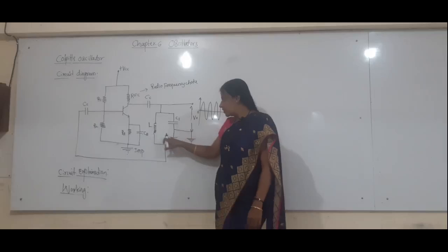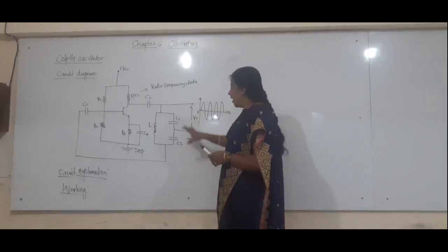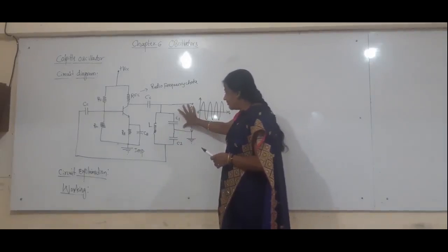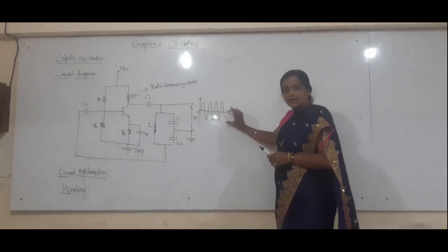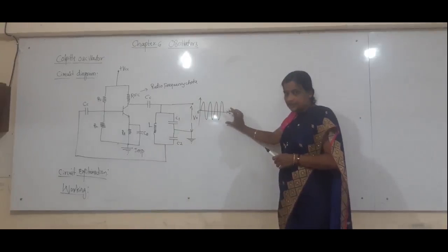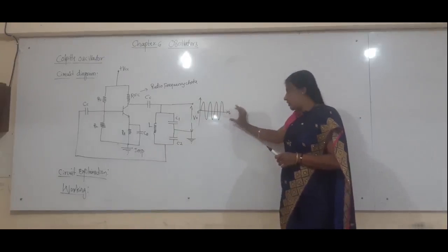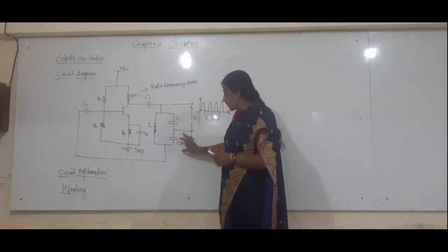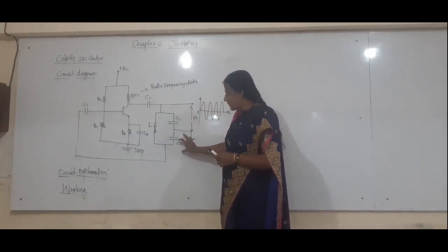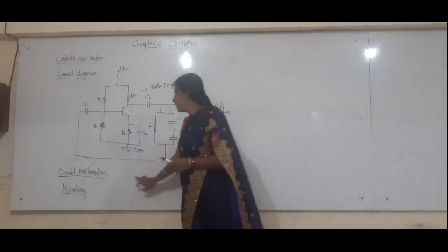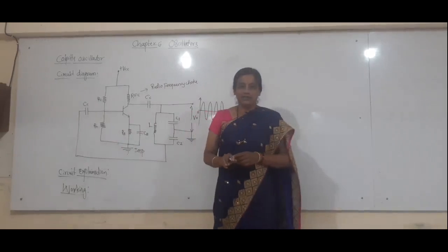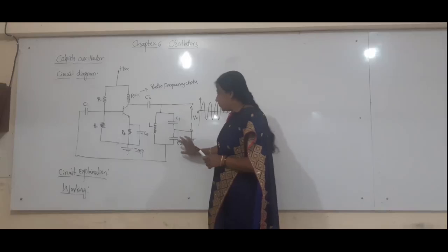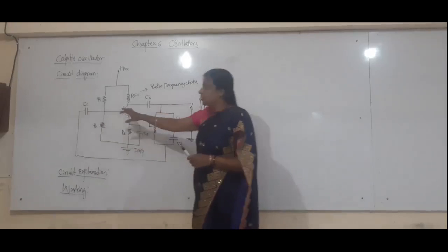Once these electrical oscillations are produced, the output, or potential voltage, across your capacitor C1 is the required electrical output, electrical oscillations of sustained or constant amplitude. And whatever the potential across your capacitor C2 is applied back to the input as a feedback voltage. So the voltage drop across capacitor C2 is applied as a feedback signal to the input